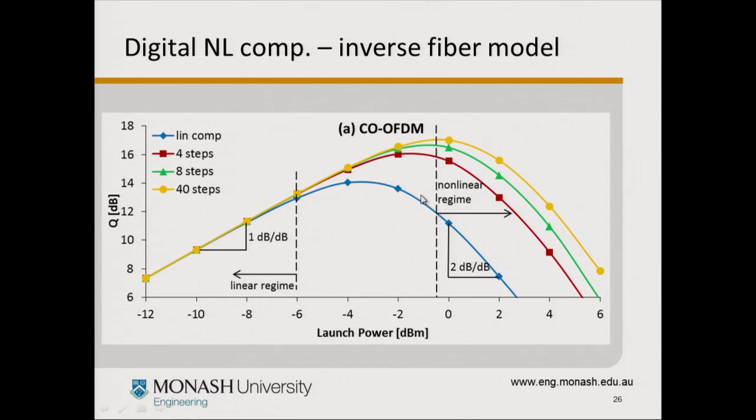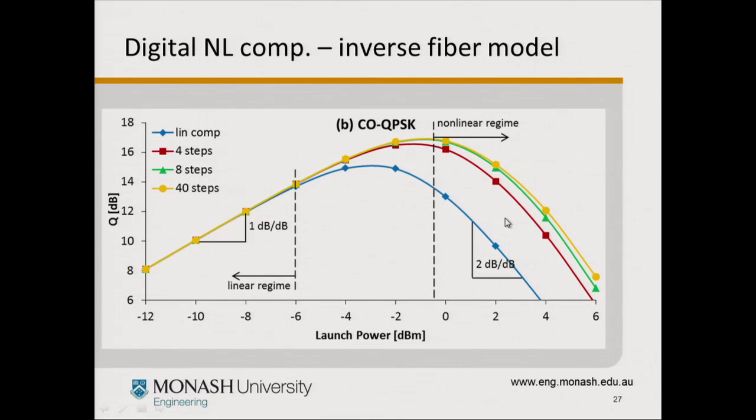And here again, to quantify the benefit that you can get, this is in a single wavelength system. We can increase the nonlinear threshold by over 3 dB, and the same for QPSK.